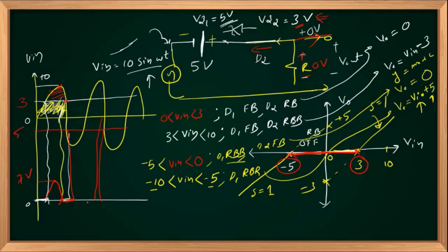And if that value is less than minus 5, because minus 5 level is this one, minus 5, so this region in between these two lines, I have an input that is less than minus 5, goes up to minus 10. So after that, I will have a 0. After that, it is nothing but Vin plus 5. But you should take care that Vin is negative.